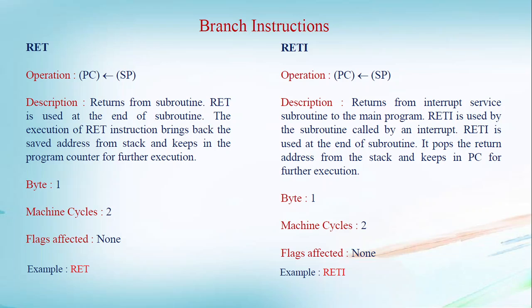Last, RET. RET means return, return from the subroutine. Basically, RET is used at the end of a subroutine called by ACALL or LCALL. The execution of the RET instruction brings back the saved address from the stack and keeps it in the program counter for further execution. It requires 1 byte and 2 machine cycles. Example, RET. Similarly, RETI is there.